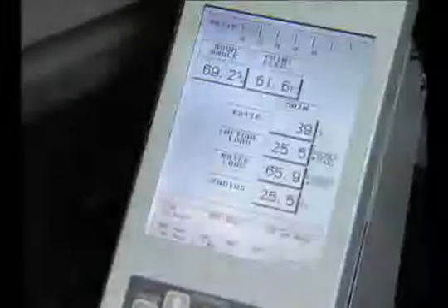Just above the display screen are two buzzers that give audio signals for the different types of warnings. At the top of the main display screen is a bar graph that starts at 60% ratio and gives the operator a visual of current load status. The boom angle indicates the present boom angle and will instantly change as boom function is operated. The point elevation display gives the operator the current point height from the ground.